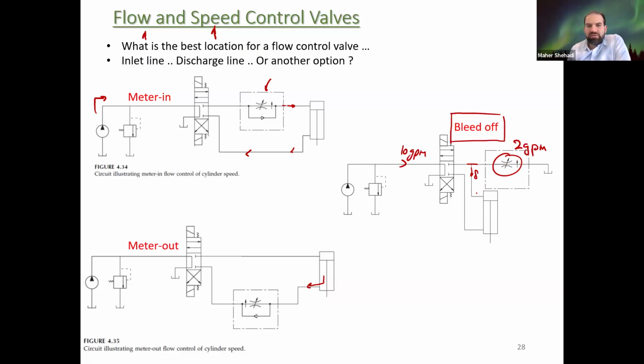Okay. So which one should you go with? Which one do you think, if you're designing and you want to place a valve, should I put it in the supply line, return, or the bleed off? So the answer, it depends. Okay, because each one has its own advantage and disadvantage. So now we're trying to control the flow. But I said with the flow, it's not just free, you can control it and you're done. No, there will be pressure drop.